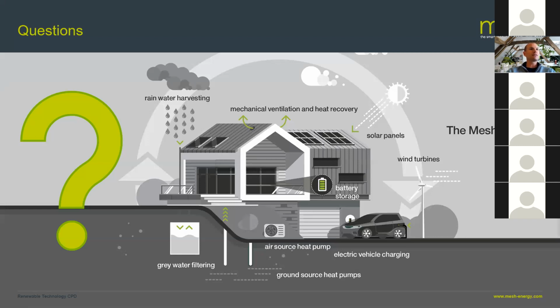Flavio's asking, I'm curious, what kind of wind turbines are being developed for residential usage? Oh, right, okay. That's a bit off tangent, but I'm happy to answer that, Flavio. Wind turbines for built up areas or domestic projects are pretty much dead in the water. There's so much turbulence in built up environments that close to the ground that they are pretty useless.